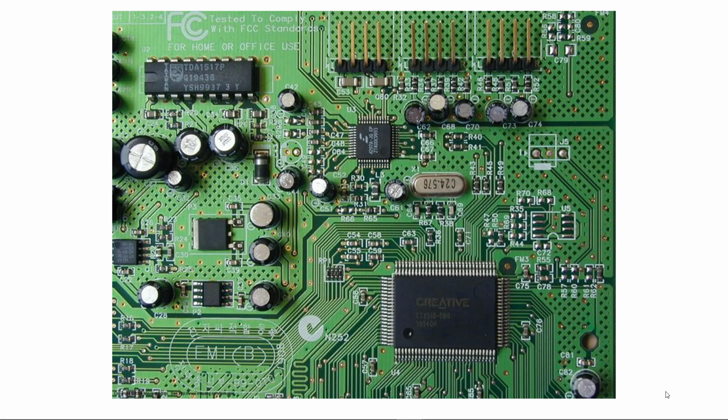MLCC, ceramic disc, and electrolytic capacitors are the most popular. MLCC and ceramic discs are commonly used for power supply decoupling. Electrolytics are commonly used in parallel and in bulk for power supply filtering. Other technologies are used for the special properties they may have, such as self-healing, small size, high voltage ability, and so on.